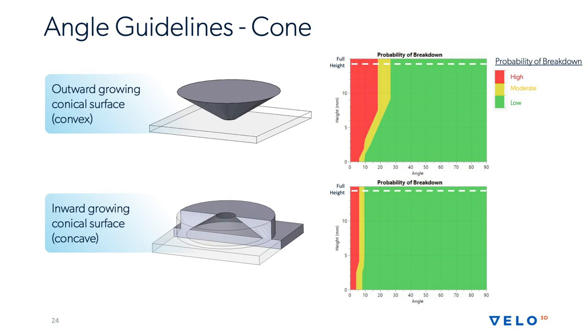Conversely, if you look at a concave surface, you've got something that behaves quite a bit differently. And what happens here, you can think about it again in the two main stressors. You have a bulk fill that's shrinking and trying to warp this inner, shallow overhang edge up. But you've got a skin process that's going to run in a ring around this, in roughly the opposite direction. The stress vector is roughly opposite. It's trying to contract and shrink it and pull it inward here.